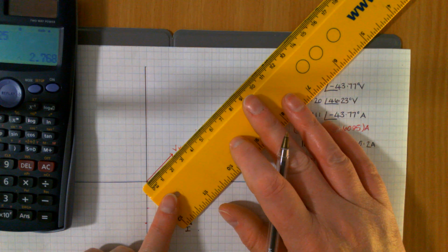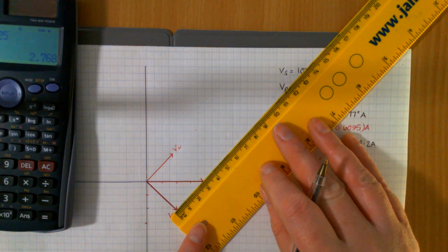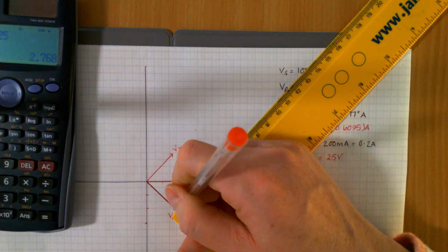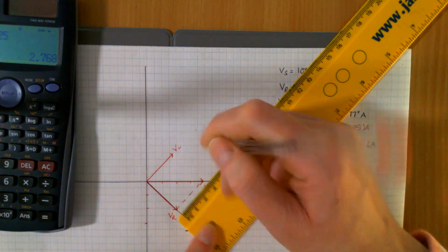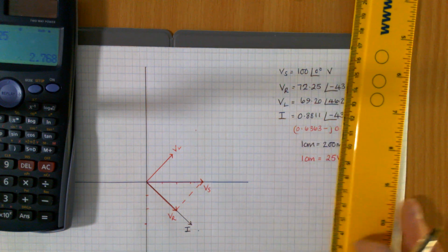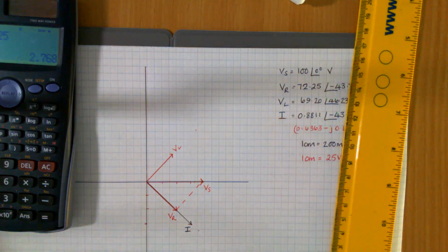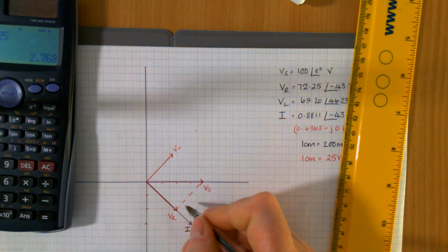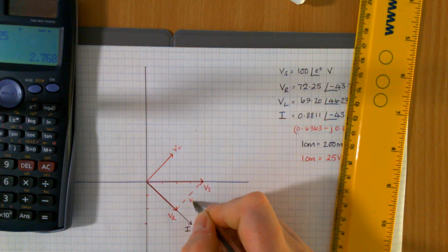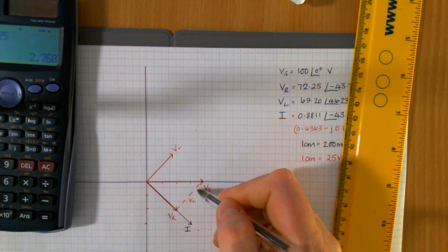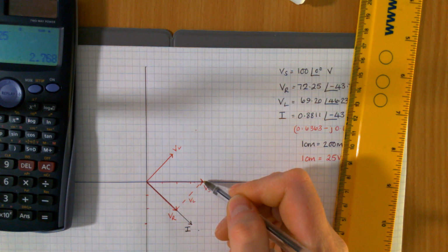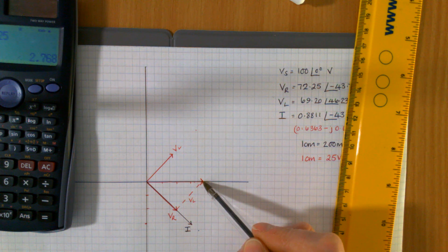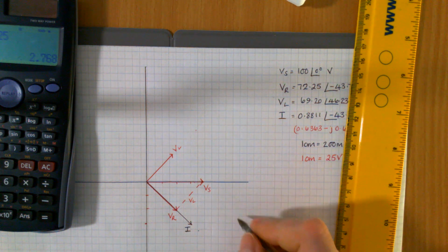And similarly on the end of that, as in a phasor addition of those two, gives you your VS. So your VR plus your VL, I've taken that and put it on the end of there, gives you your VS. So that proves the phasor addition of those two phasors gives you that VS. So when you add VR plus VL as phasors,